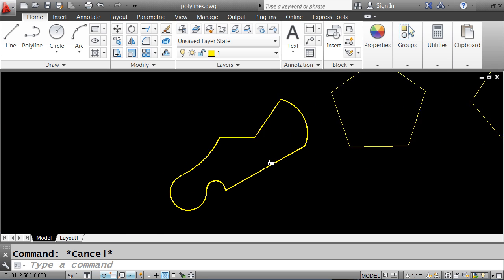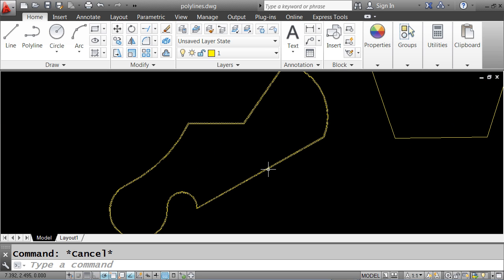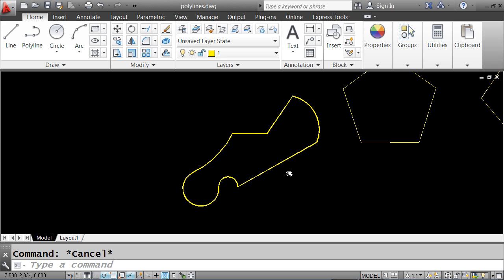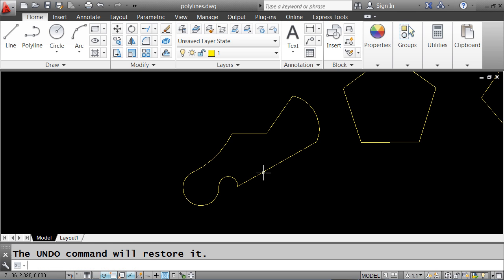I'm going to zoom up on this polyline here. This polyline looks like it has width, it has arc, it has lines. It probably had a radius, it probably was closed. And I'm going to go in and explode polyline. I know it's not a great technique, but I want to see, oh, wait a second. This was a line, this was an arc, this was a line, this was an arc, this was an arc. So there's between lines and arcs, and it could be polylines that originally created this object.